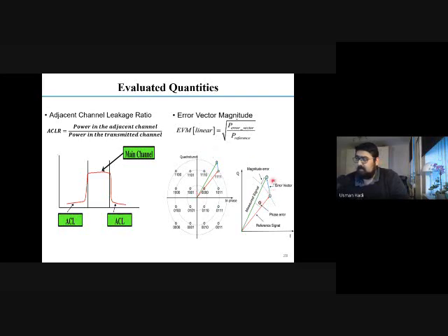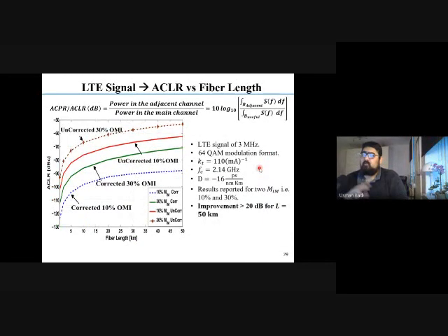For example, here, this is the measured signal, this is the received one, and this is the reference, which is the transmitted one. And then you can find the error vector between these two, as we generally used to find in high school. So this is the error vector between the transmitted and the received constellation. That is called the error vector magnitude, and it is generally used as a performance metric of the system. So just to give you the idea of what ACLR and EVM are.